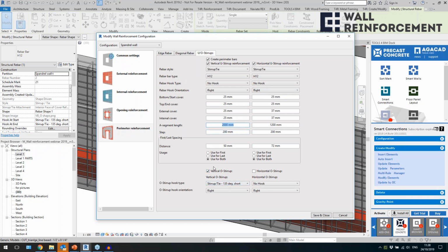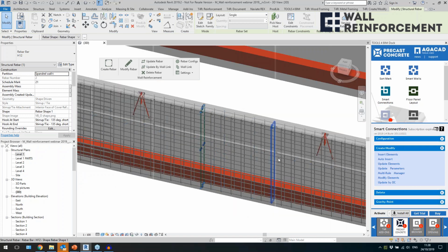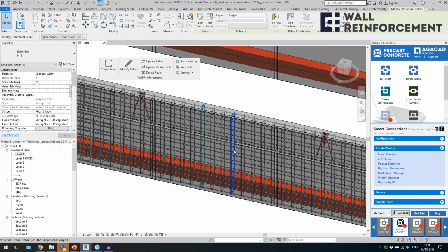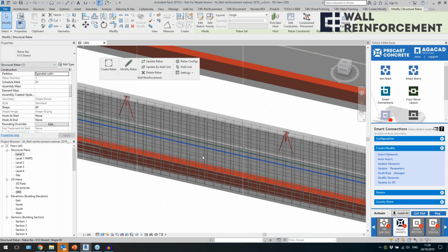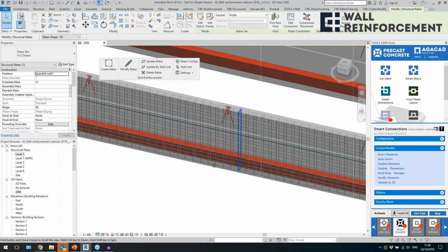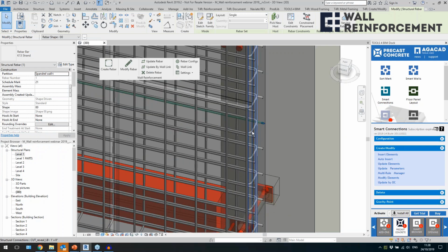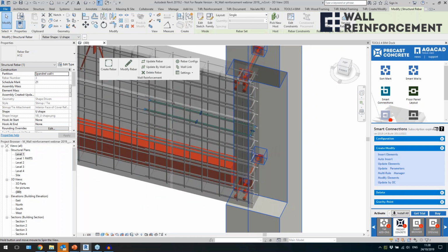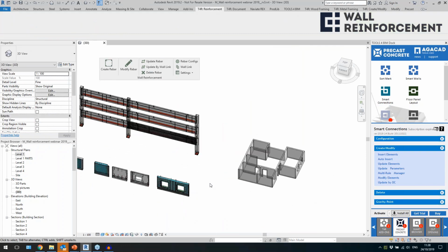So that's why I'm getting O-shape reinforcement over here. So now basically I have O-shape reinforcement in that direction, straight bars going as, you can call them strand or whatever if you use them. Maybe it's more in the United States, but anyway. And then at the end, I have also U-shape bars, right? So just distributed like that. So that's another example, right? How can you use that?